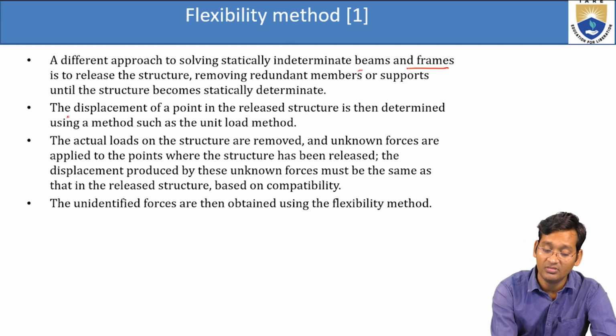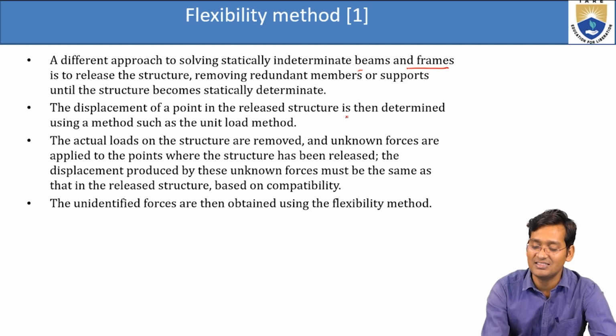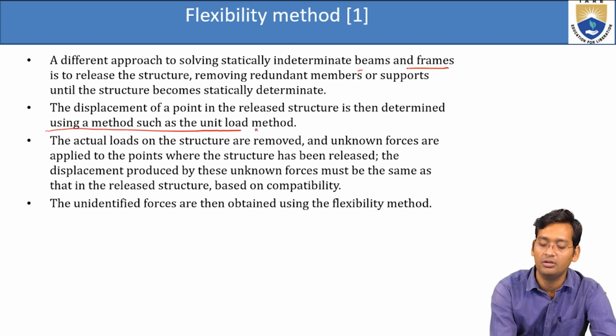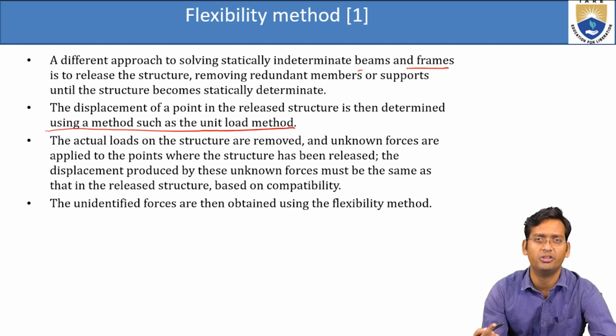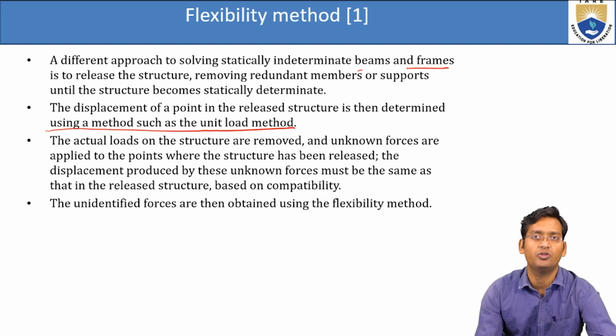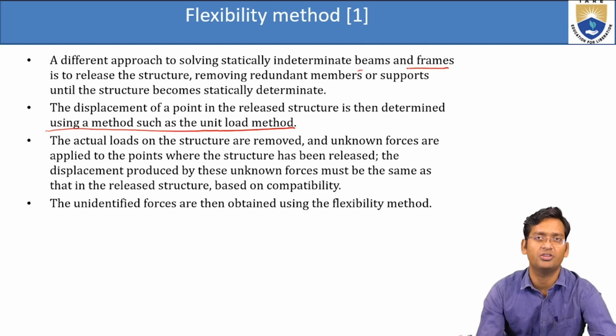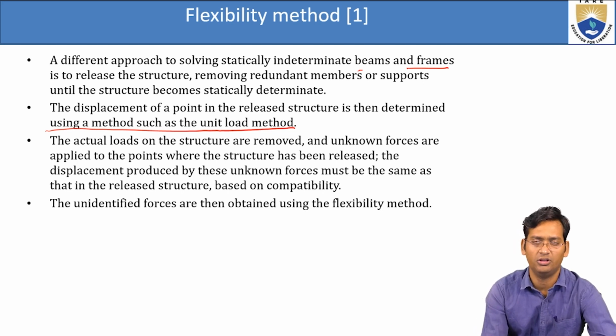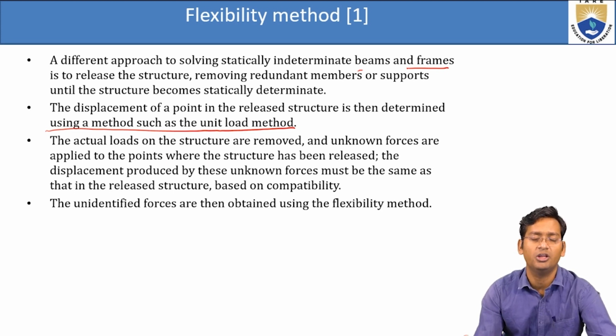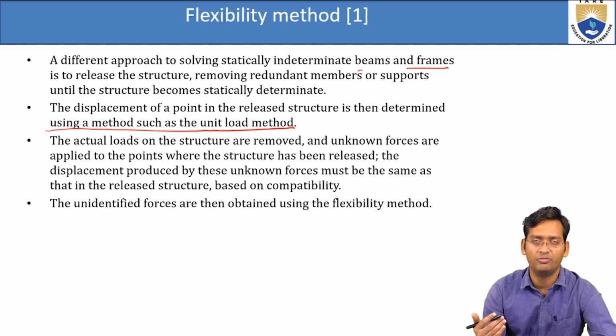So here, the displacement of a point in the released structure is then determined using a method such as the unit load method, and not only that one. Whatever methods we have seen, we can use once the structure becomes statically determinate: unit load, total potential energy. In the previous video we saw the total potential energy method, and the Rayleigh-Ritz method and unit load method. Whatever the methods are, once the structure becomes statically determinate, we can use them.